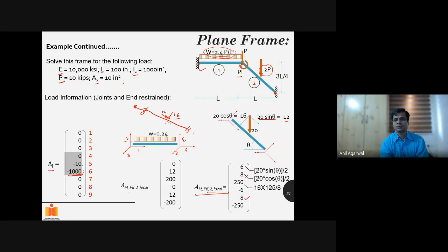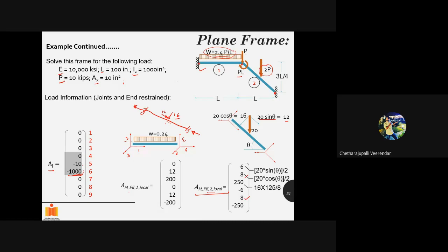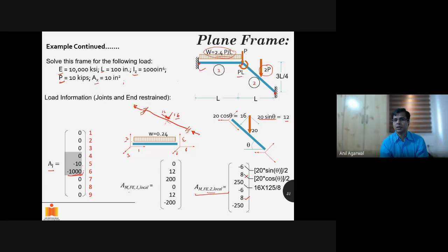So 12 kilonewton is being applied in the axial direction. That has to be resisted by both sides. And since it is acting right in the middle of the length of the member, both sides will be offering same resistance. So how much will it be? 6 on each side. Half of 12. Since this is in the minus x direction, I'm calling it minus 6 and minus 6. Got it? What else needs to be handled?